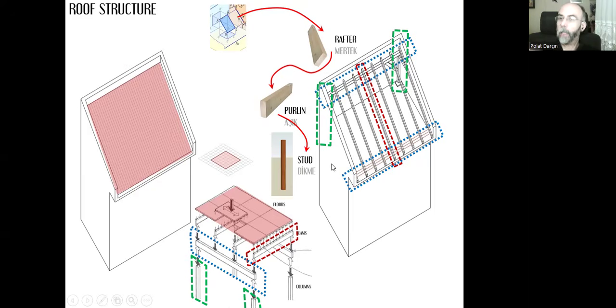And each purlin at that level, in the different level, here, that purlin is standing right on the floor. We have this floor surface, and it's the structural system of the start of the building. As you can see, this purlin here at the eave level, it's standing right on the floor. It's not elevated from the surface of the floor, so we don't need any vertical studs. But this one, it is elevated so that it will create the ridge line, and it's being supported with these two studs on each end.